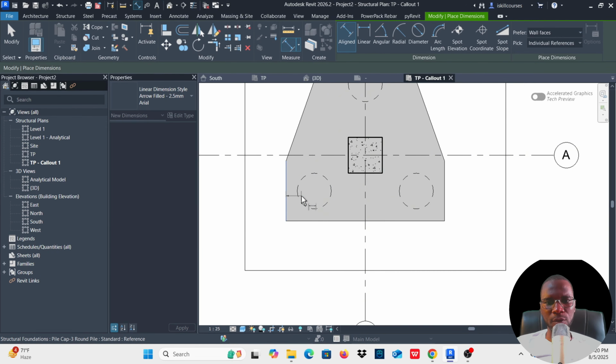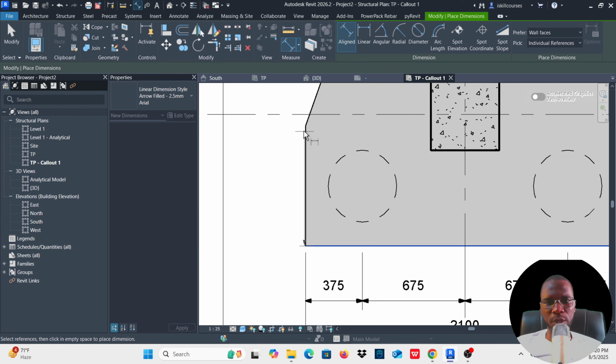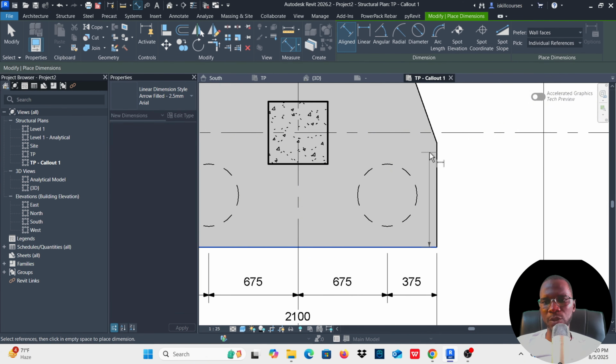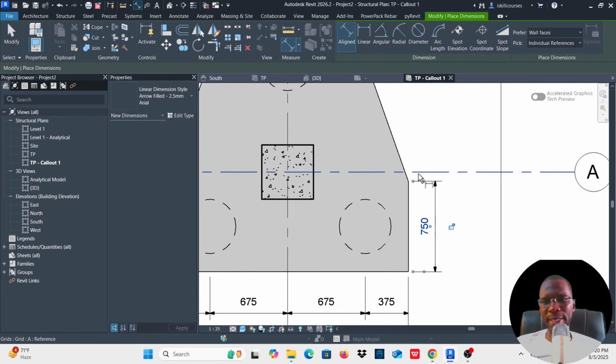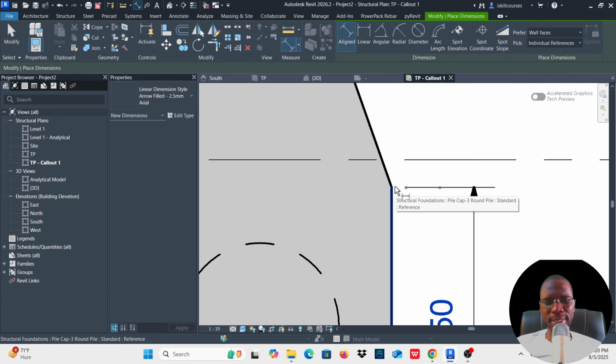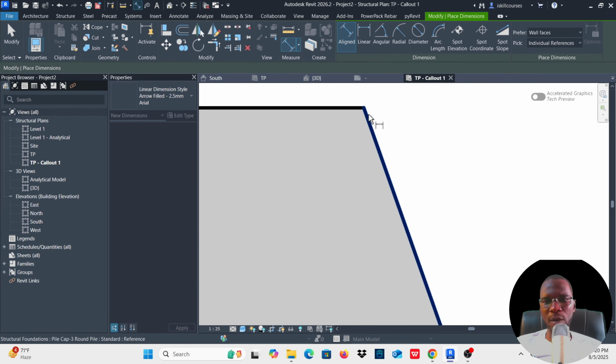Annotate there. I can just detail it like that if I want. Add my detail there. Select this one and add my detail there. Then this one, I'll pick this one, but to pick the dot there, make sure that the dot highlights and pick it. Pick this one, make sure that the dot highlights and pick this one. Now for this one, which is slanted, make sure that you pick the dot. When you place the cursor there, press Tab until the dot highlights, then click, then go to the top there, watch for the blue lines there, but the dot has to appear.